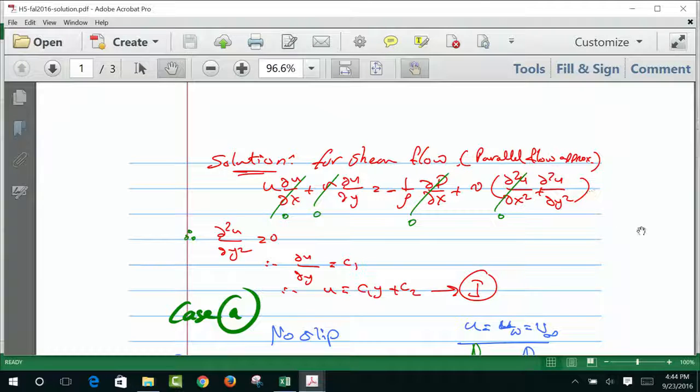There also used to be, what's one thing missing here? What was here? The g, the gravity, the body force, right? So we neglect gravity in most microflow problems because the scale of those things is too small for gravity to be that important at all. But in today's class we will actually include another body force. That one would be the electrostatic force. Yes, gravity is small, but electrostatic force does not get that small.